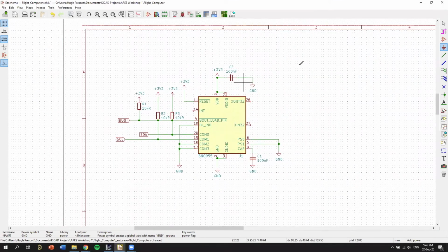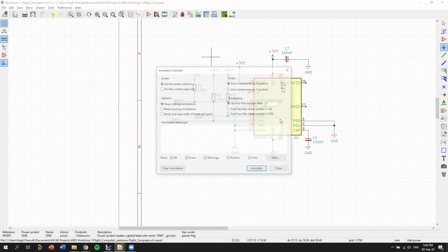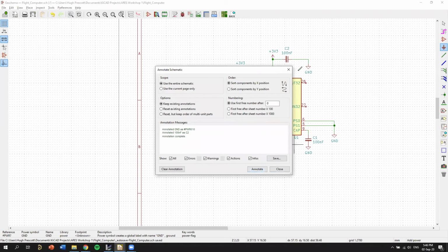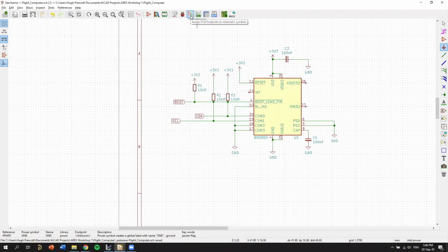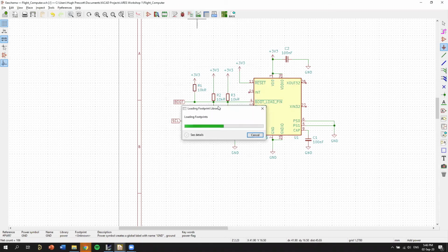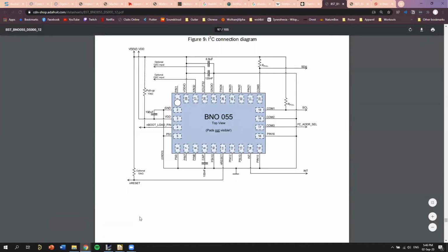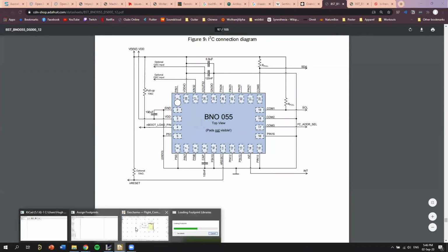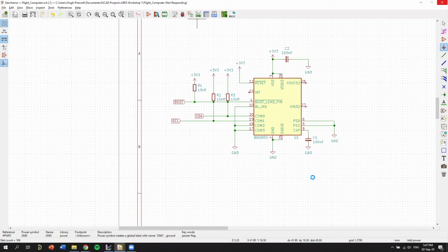Let's work with this. Let's just get it on the PCB. So we've annotated everything now that we added that capacitor, and now we want to do our footprint. If you remember last week, we talked about different footprints for our passive components, our resistors and capacitors. There's 0402, 0805, just different sizes. So we're just going to give them some standard footprint.